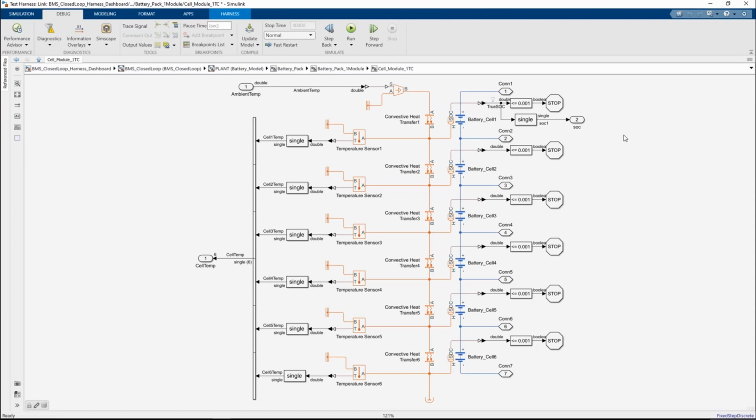What makes this cell representative of a real-life lithium-ion chemistry? Well, inside each cell, there is an equivalent circuit represented by this battery block, whose topology and parameters should give me a response equivalent to the one I would observe experimentally. The equivalent circuit components should include temperature, SOC, and possible aging dependencies. The previously discussed method of parameter estimation naturally can and should be applied here.